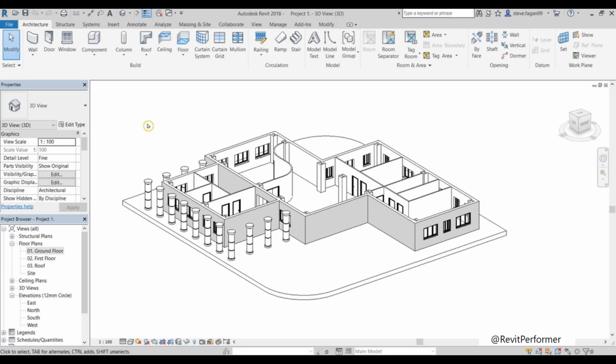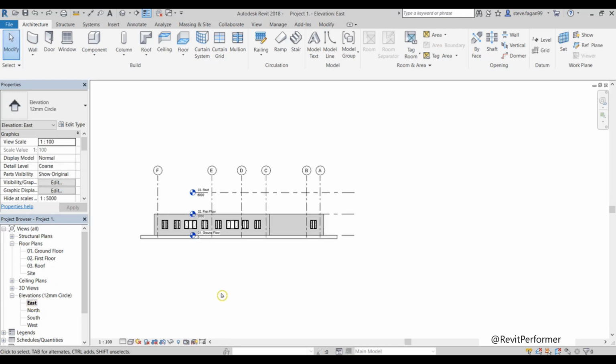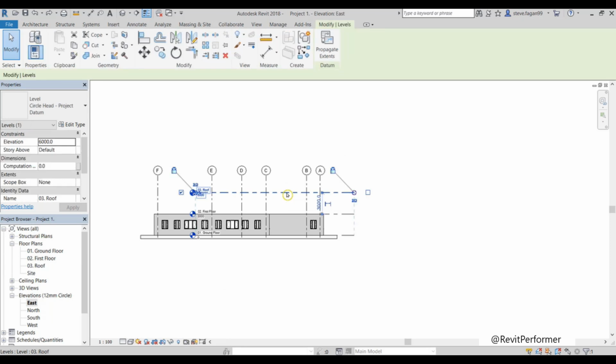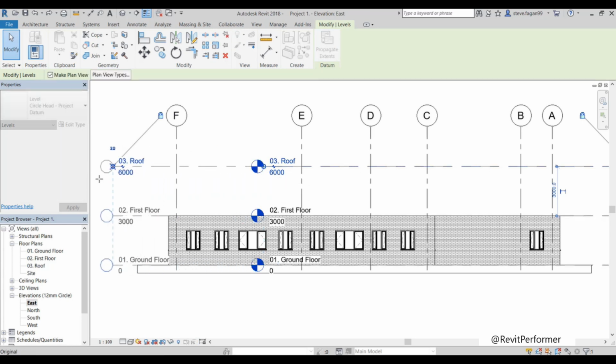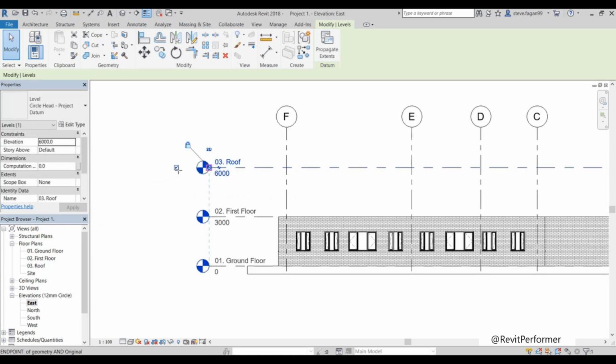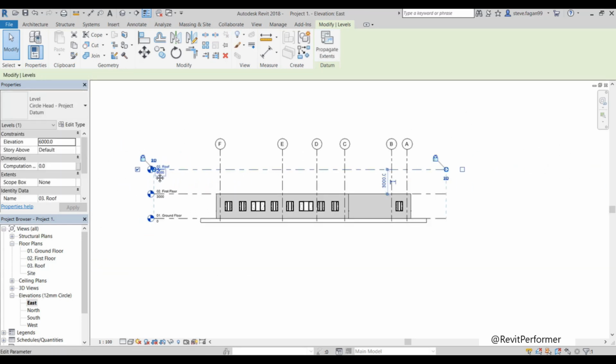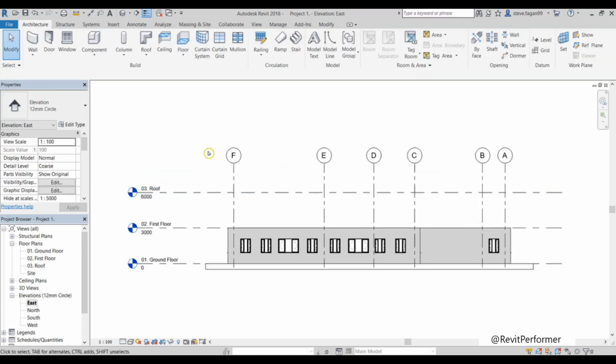As well, to demonstrate the increase in height, I'm also going to open up an elevation view. So any one for now. When the east elevation opens, I'm going to reposition my level. So I'll select one of my levels, zoom in, grabbing the open grip and dragging it to the side. So I want all three of my views to be open simultaneously.